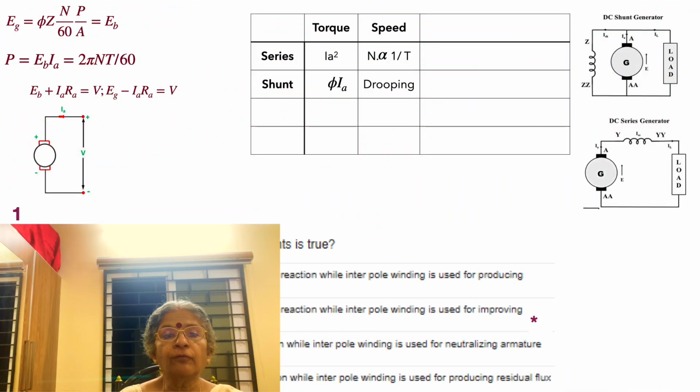This formula is for the generated voltage when you are considering a generator, or for the back EMF, which is actually a reaction of the motor with respect to whatever it is doing, when the power supply is applied to it, wherein the conversion is happening. In both these aspects, the voltage that is developed in the armature remains the same. So it's very important, and it is one of the most important equations that we apply, even subconsciously. So we have Eg, which is equal to Eb.